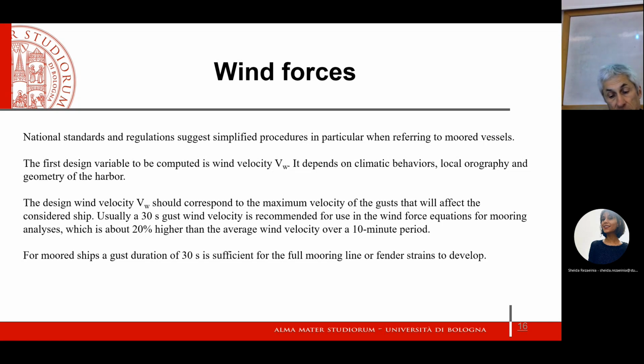Variability means that if you measure the wind velocity over a time frame, you average it over that time frame, you get an average that is lower than the max during that time frame. So, for instance, the wind velocity is generally measured as an average over 1 minute, but then it means that if you look at 10 seconds, you have a higher max.